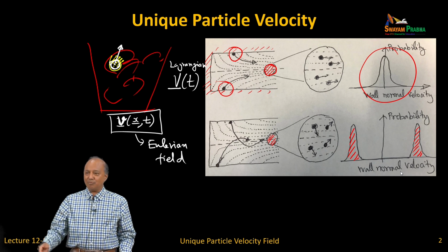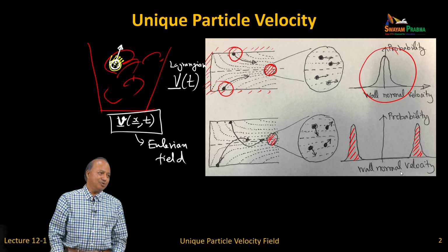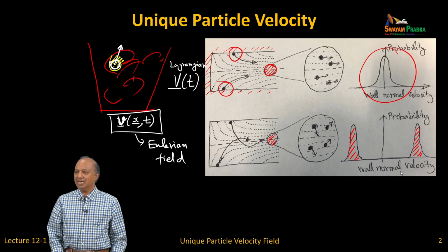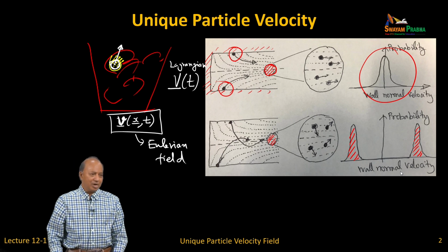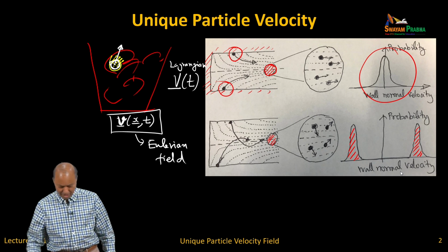Now, one thing that I am going to now talk about, if the Stokes number is really small, you don't even need to do Euler-Euler. Okay? You can do even cheaper than that. There are methods called dusty gas approximations or equilibrium Eulerian method. That's what I want to talk about next.